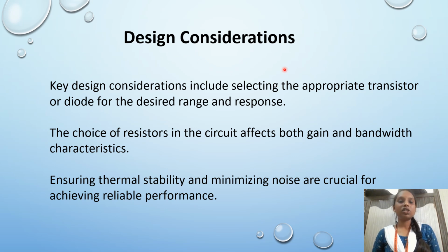Next, design considerations. What are the design considerations of log amplifiers? The key considerations include selecting the appropriate transistor or diode for the feedback in the circuit for the desired range and response. The choice of resistors affects both gain and bandwidth characteristics. Ensuring thermal stability and minimizing noise are crucial for achieving reliable performance.